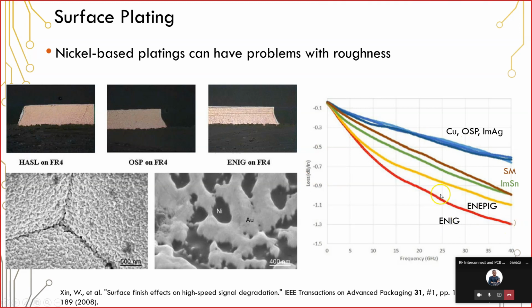It's once you get out here into these much higher frequency ranges, so 24 or 25 gigahertz, where you start getting into radar, now it really matters a lot. And you can see there's a really big difference here. It's a half a decibel. Well, that half a decibel of loss per inch can really limit your routing lengths in these designs. And it gets even worse as you get out to higher frequencies, as you can clearly see from the graph.